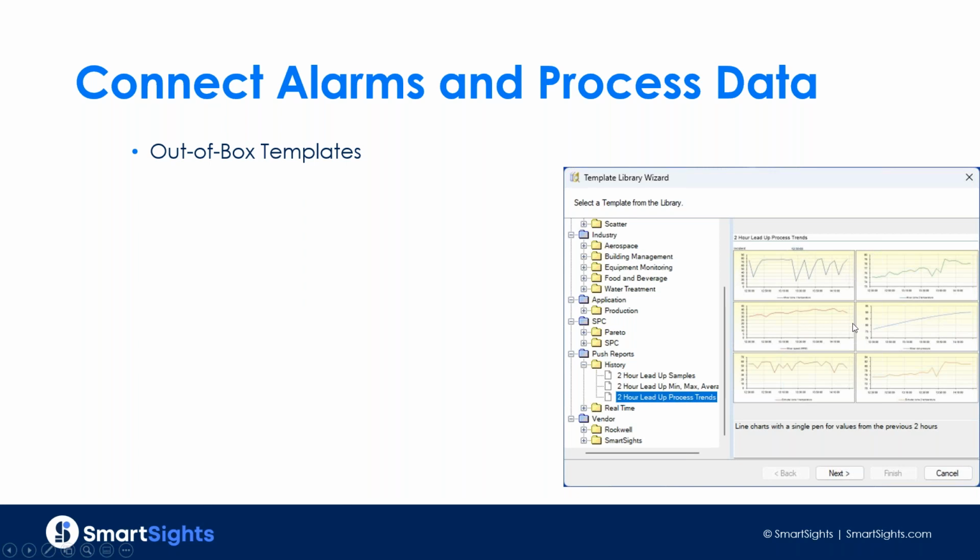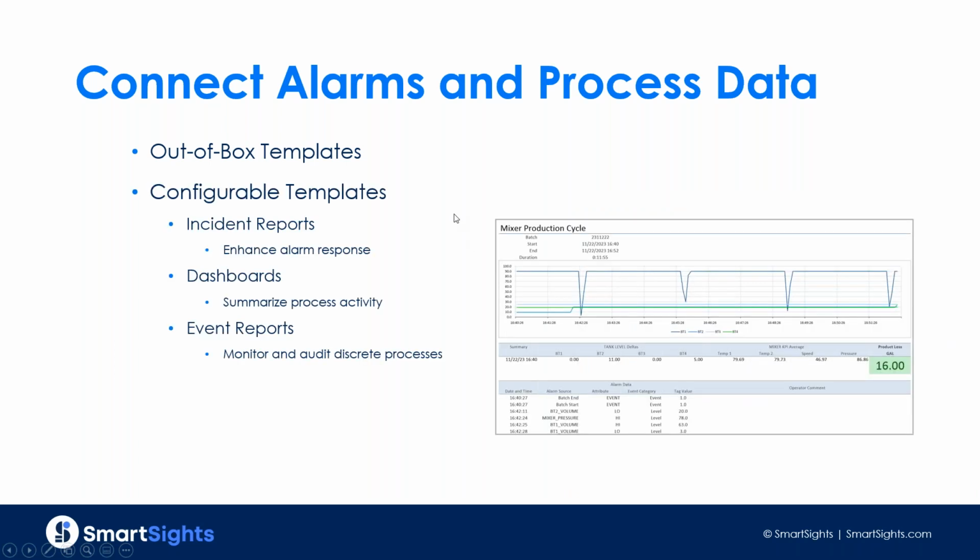So this is relaying information, for example, like if you have a high or a low tank alarm, right? You might want to know that the value's been steadily trickling down or up, or if it's actually experienced some volatility, if there's other disturbances happening on a related parameter like a pressure or a temperature. This gives you more information on the root cause of the alarm. Understanding what's happening helps you solve the alarm or resolve the condition more effectively.